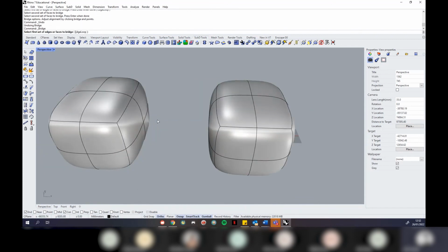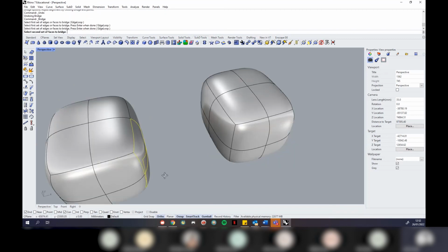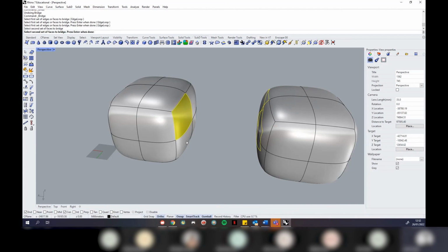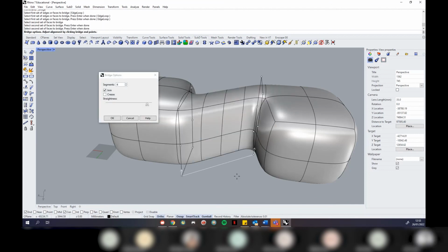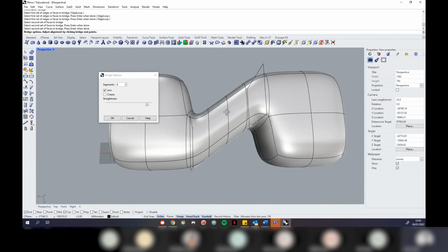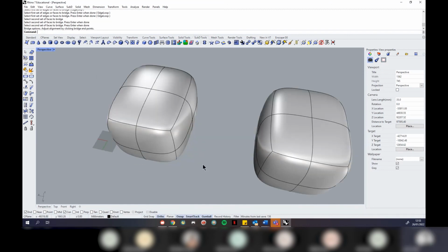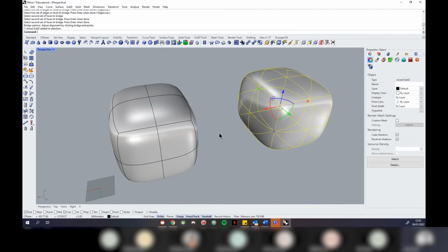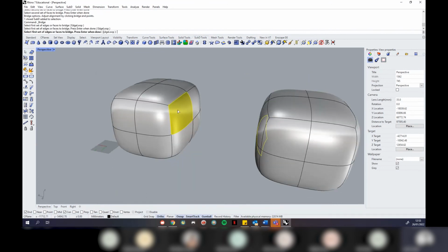And again, it's not just faces this works with, it can work with edges as well. And they don't have to be parallel. But the number of faces that you're connecting do have to match. So for instance, if I'm connecting these two faces here, I'll define that as my first set. I could tell that to connect to these two faces, and that would work. That would connect those together. If I were trying to connect just a single face to two faces, it doesn't work.